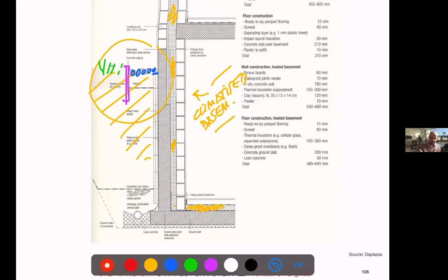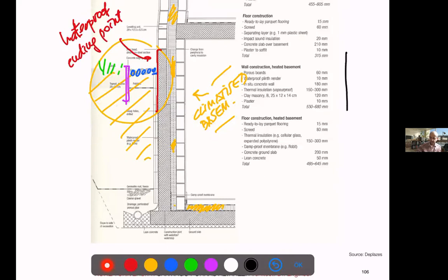We have another difficult point in terms of design, which is the waterproofing. Waterproofing is always ugly. So, the waterproofing ending point, right? If you have the wall, you have the waterproof layer and then the gravel. If you're not very careful, this is an open point, so the water can go in. So sometimes we put a kind of clip, something which covers, and this should be enough. Sometimes it is hidden under, so sometimes you will see it hidden.